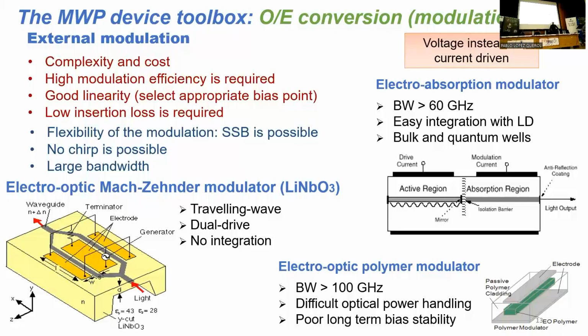to use an electroabsorption modulator. But this is not what we call an electrorefractive modulator. This modulator works by changing the absorption rather than the refractive index or the phase. So it's inherently very nonlinear, and this is the last thing you want from a modulator. In analog applications, you want a very, very linear modulator. So with the Mach-Zehnder, you can choose your bias point and actually get quite reasonable linear operation. Okay.